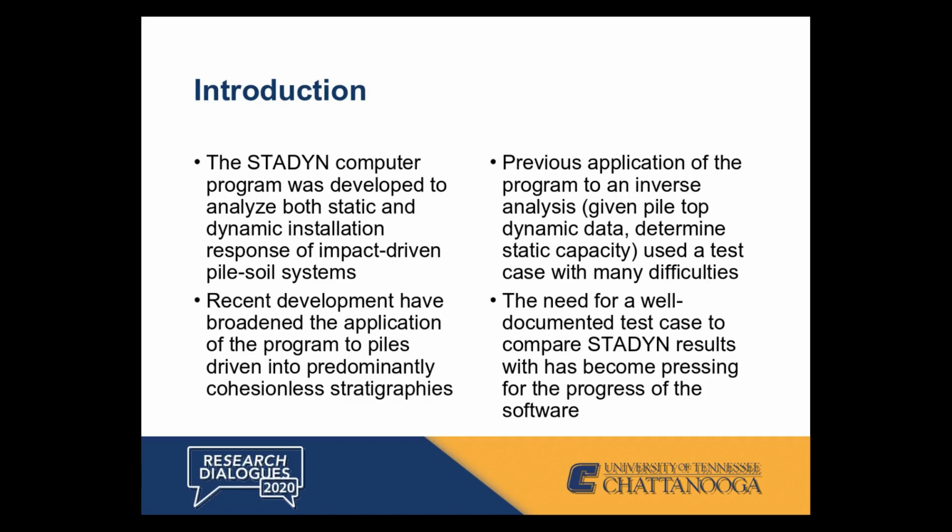This program has been worked on for the last 5 or 6 years. In recent developments, we've broadened the application of the program to piles driven primarily in cohesionless stratigraphies. The original study was mostly with predominantly cohesive stratigraphies, but now we're branching out. Previous applications to an inverse analysis used a test case from the New Orleans area, and it had many problems, not the least of which was there was no static load test to go with it. There were other problems with the pile, and you can look at my earlier work on the subject.